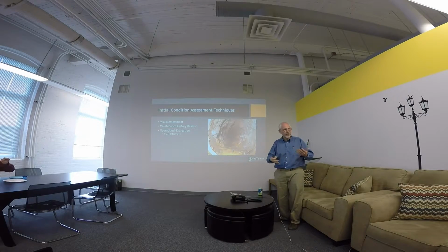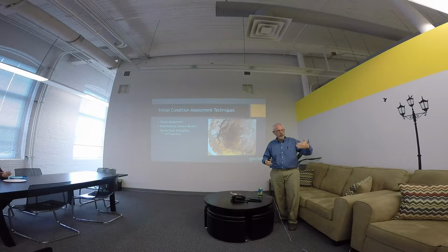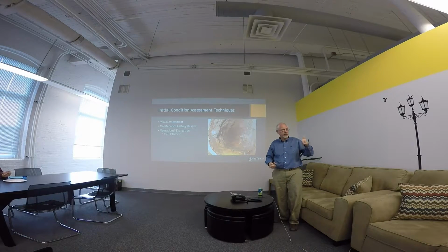So it's an operation. The second thing is it's not only when you're looking at condition, that buildup also impacts fire protection, because you can't get the same fire flow through this pipe that you would if it was a brand new pipe and opened up. So a fire hydrant, you typically want to get 1,000 gallons. This pipe would probably only limit you to 500 gallons.